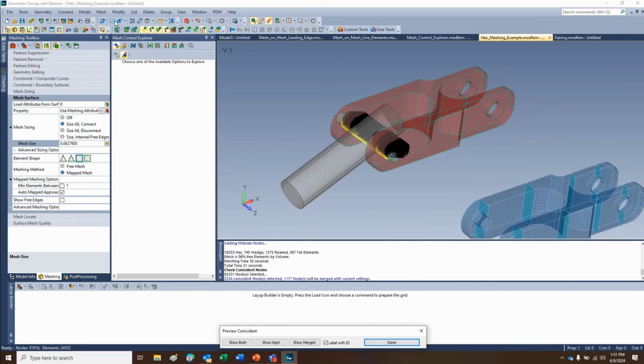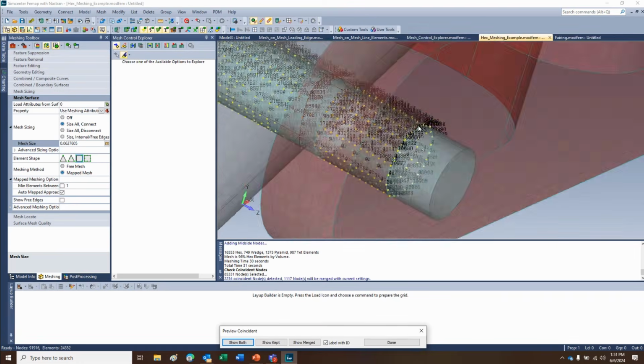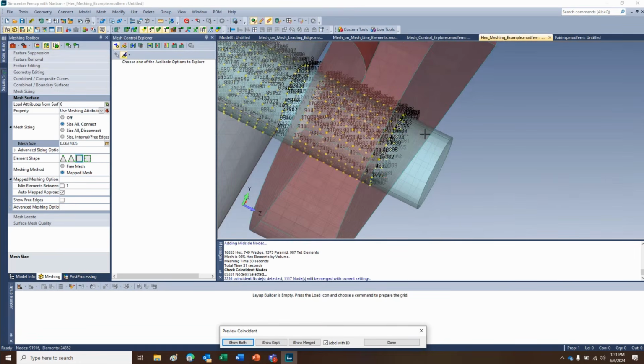And what you can actually see is it just knew to match the nodes on both sides. Everywhere where it knew there was an assembly, based on proximity, it just decided to match the nodes there. So not decided. I mean, that's the way it works. So theoretically, you can mesh whole assemblies with a hex dominant mesh and have it all be combined, so long as, you know, think about if you were going to do an automatic connection on an assembly, something of that nature.